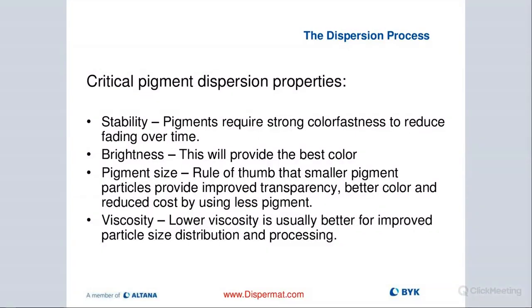So we have to disperse or mill longer to really get to the particle size that we're looking for because it's just more difficult to put in the energy needed. Therefore, we want to look at the formulation to bring up the viscosity into that nice range, 2 to 8,000 centipoise. That really helps us from an energy standpoint.